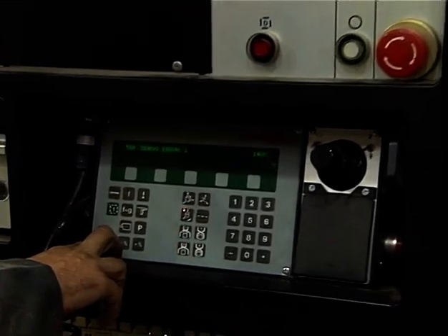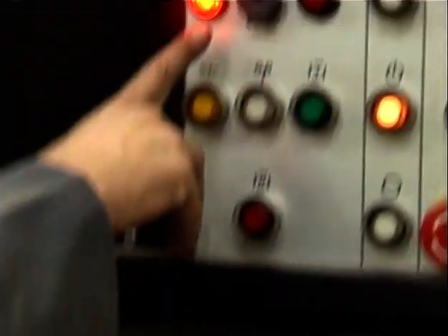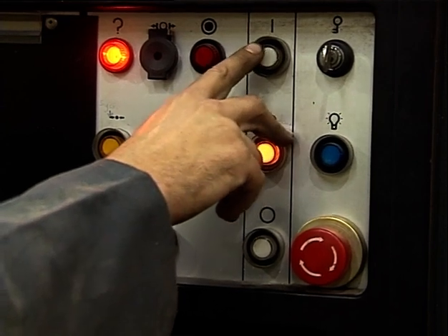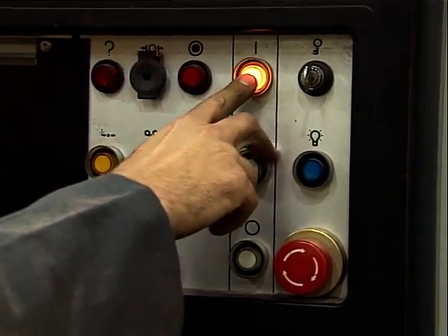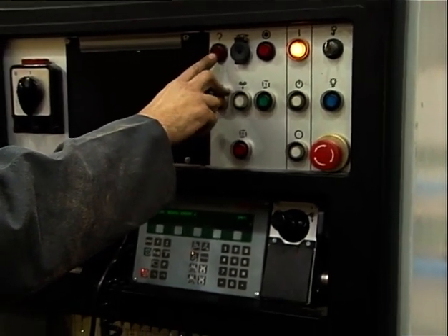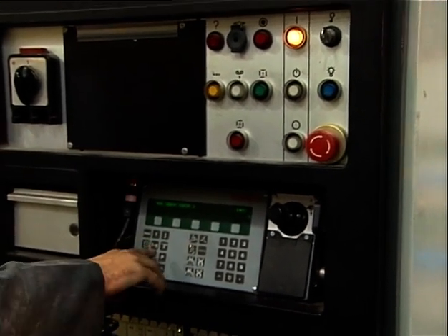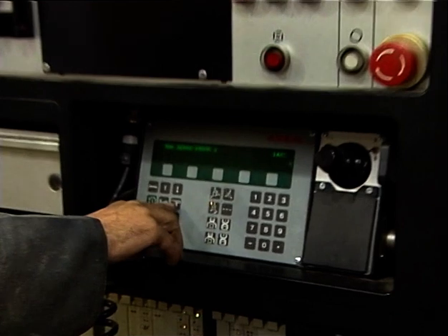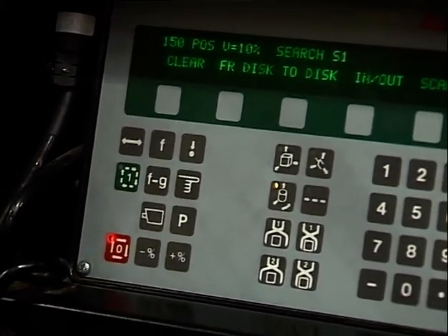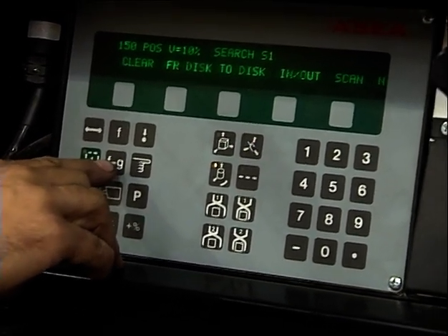The first thing you must do, you see the robot is in the 0 position and he is giving also a problem, is to start the robot again by pushing the 1 button. And you see that we have solved in the first stage the problem. Then we are going again to the teach panel. We are going to the manual mode by pushing the hand button. Thereafter, we push on the edit button, the FG button.